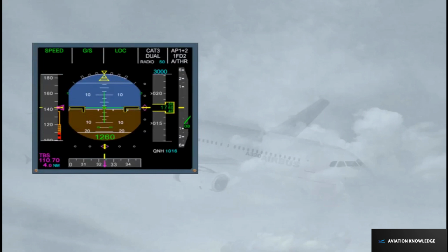When the autopilot flight director pitch or vertical mode controls a vertical trajectory, the autothrust controls the speed or Mach. Note, if both autopilot flight directors are off, the autothrust controls the speed.